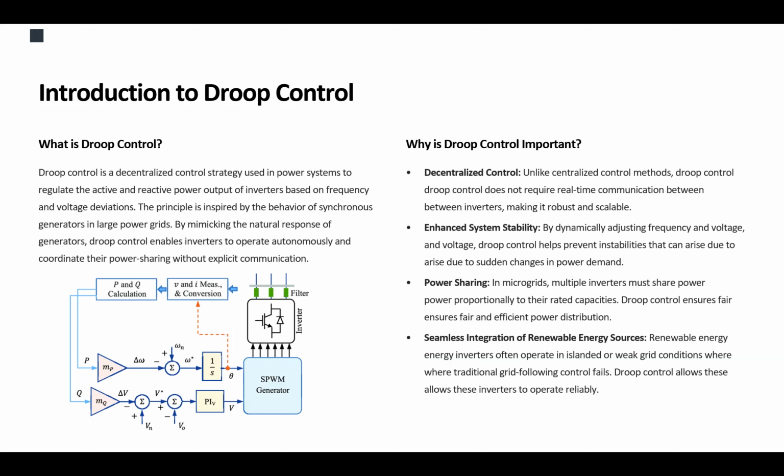In the synchronous machine, or basically the rotary machine, not just synchronous, when they want to control the speed of the machine based on the output power, the mechanical power that they have to provide, normally they use a speed regulator and control the rotational speed of that rotary machine in order to dictate how much power or how much torque they provide at the mechanical output of their machine.